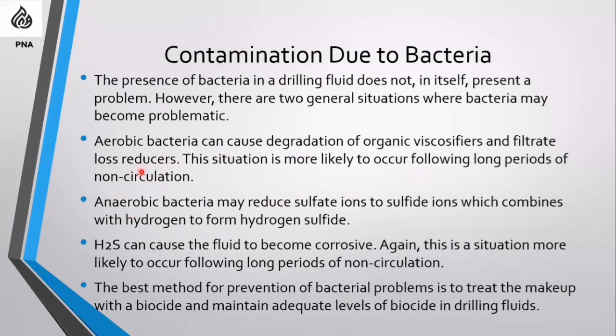That's why before logging operation, before running casing, or before pulling out of the hole for a long time, we put biocide in our mud to prevent the bacteria.